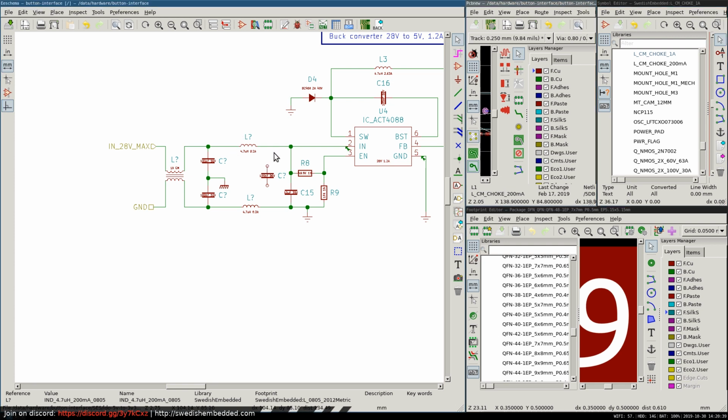But the thing with the way it seems to be in reality is that you never see this kind of configuration in final circuits, because this thing actually has leakage inductances which simulate the behavior of these inductors. So this common mode choke actually replaces the differential mode filter that you would be putting here. So we can remove this, and we don't have to worry about them, and we can just worry about the common mode choke.